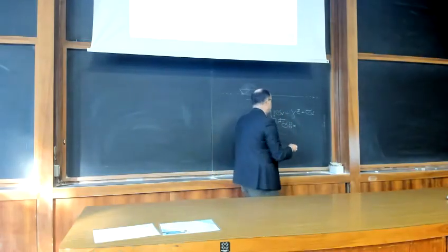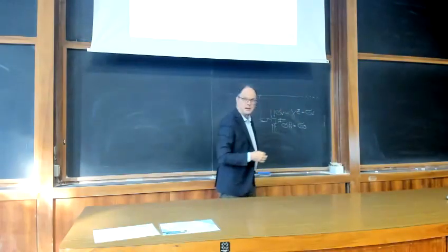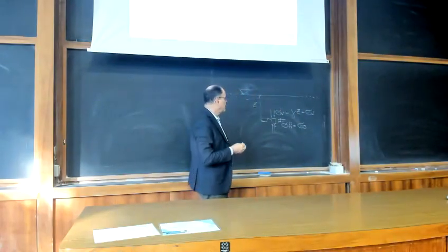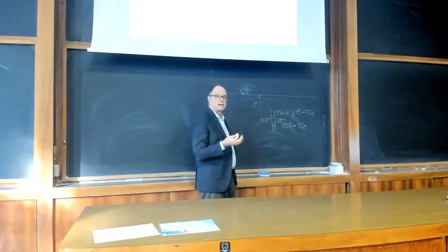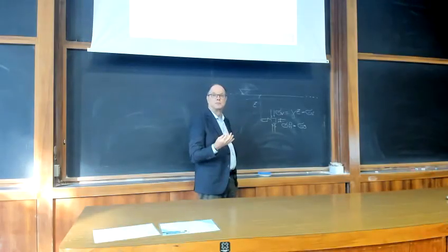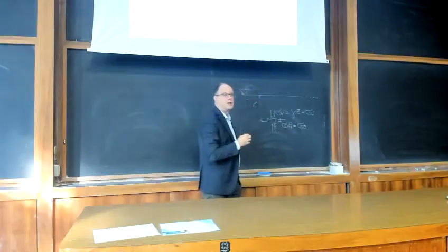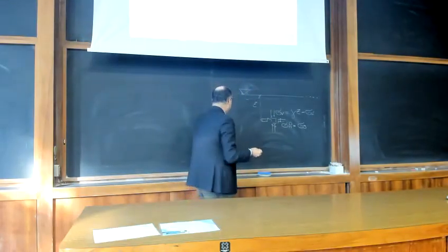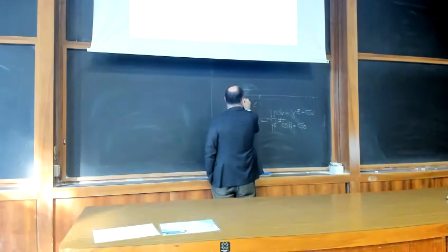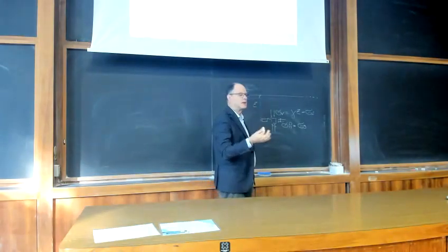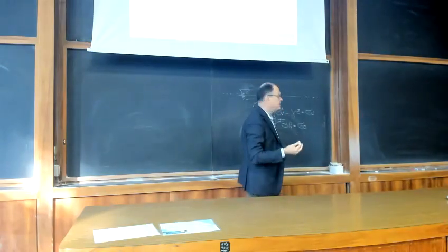So let's say sigma 3, if the horizontal is less than the vertical stress. Now, the horizontal stress, we know it is not statically determined. So it can be any value, because you can guarantee the horizontal equilibrium for any value of the horizontal stress. And if you think that this is a fully saturated soil, we have to distinguish between the total and effective stresses.